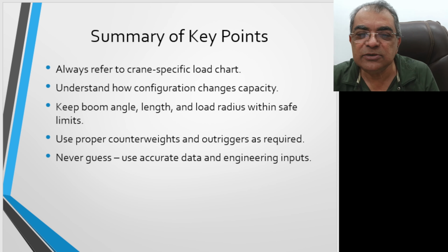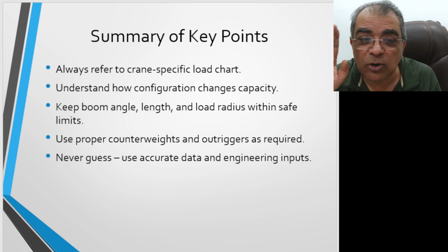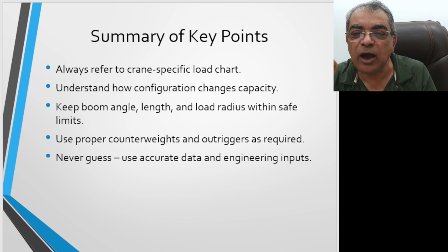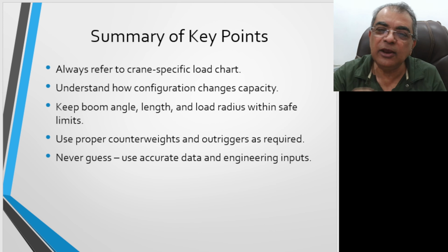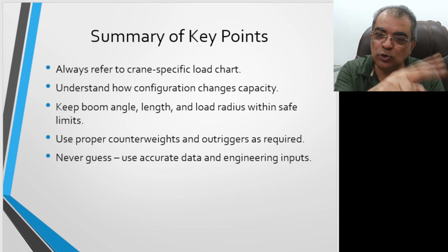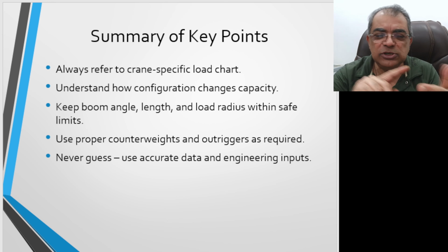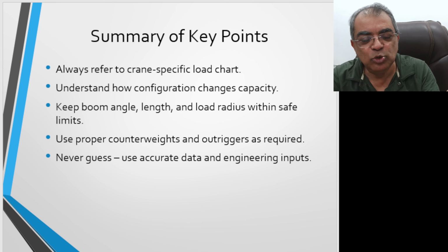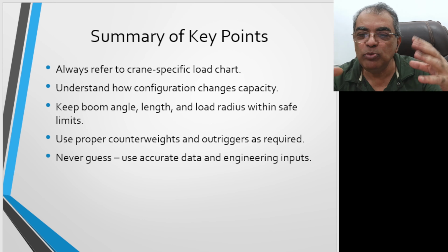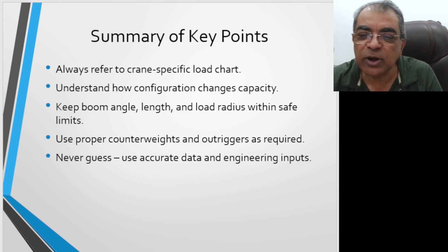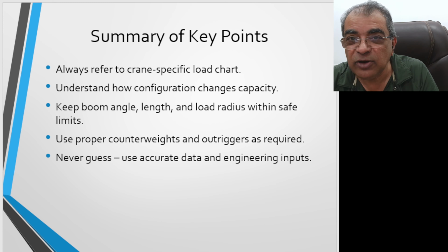To summarize my key points, always refer to the crane-specific load chart. Always understand how configuration changes capacity. If you are at site, just try to take a load chart and see what I have shown in one of the charts. You just see how the boom length and boom radius change, and the lifting capacity changes. Keep boom angle, length and load radius within the safe limit. Use proper counterweights. Counterweight is very important.